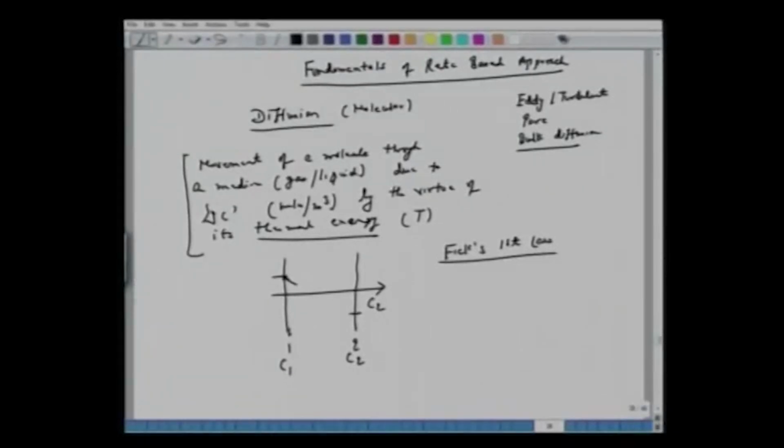which is molecular diffusion. We make a note, it's prevalent in laminar flow. So let's say in a tube, if you have done hydrodynamics, we said earlier, the Reynolds number is less than 2100. It's a very slow process. So we are talking of molecular diffusion, unlike say turbulent.